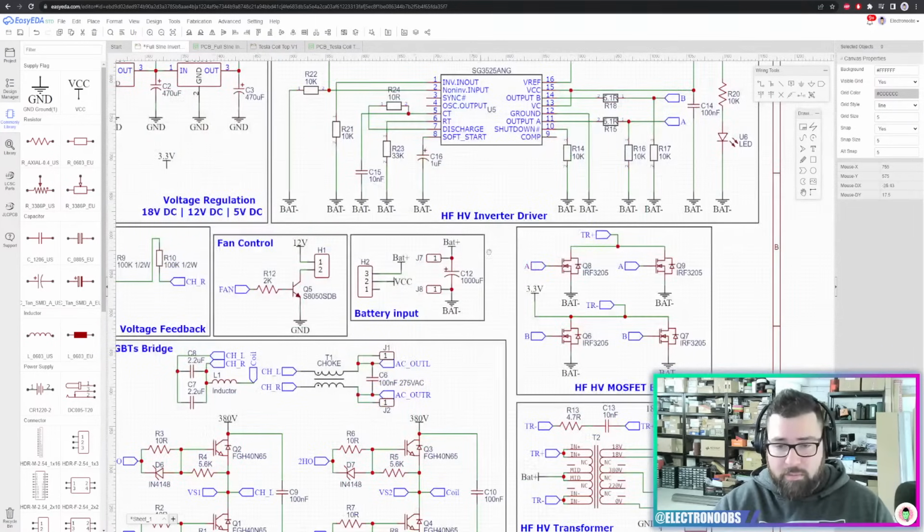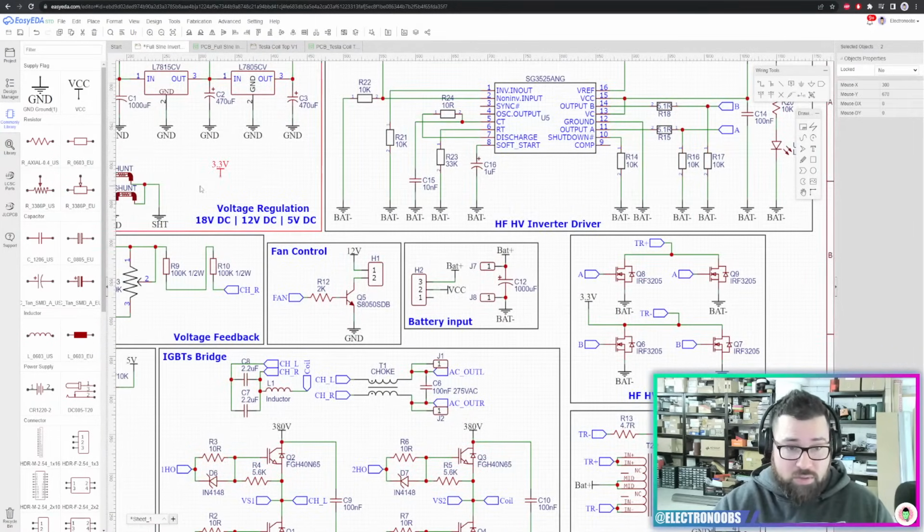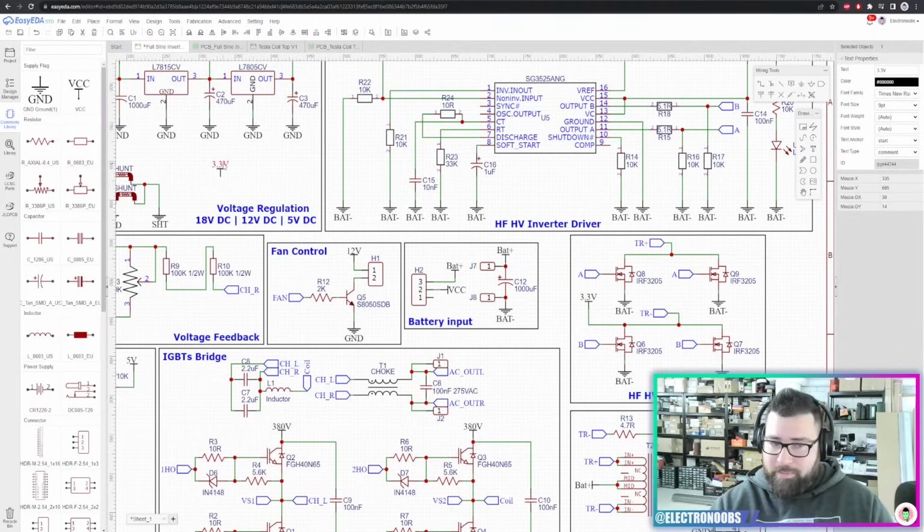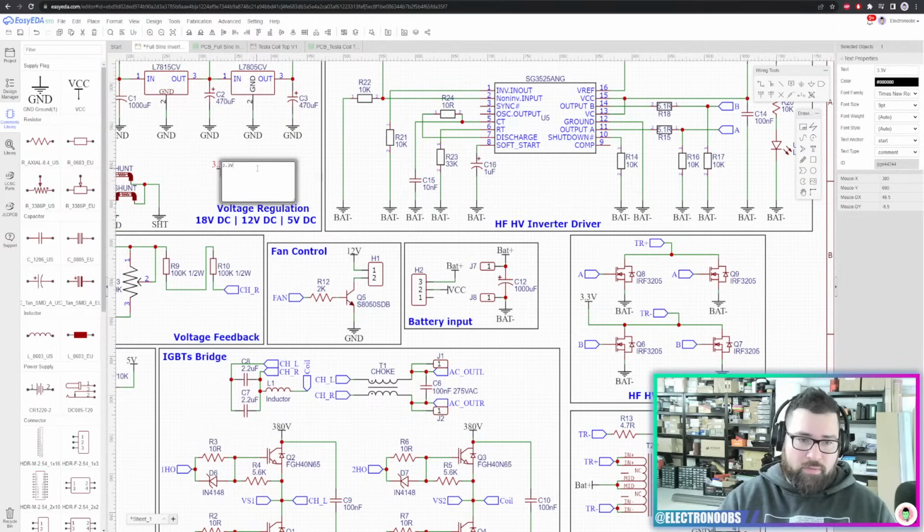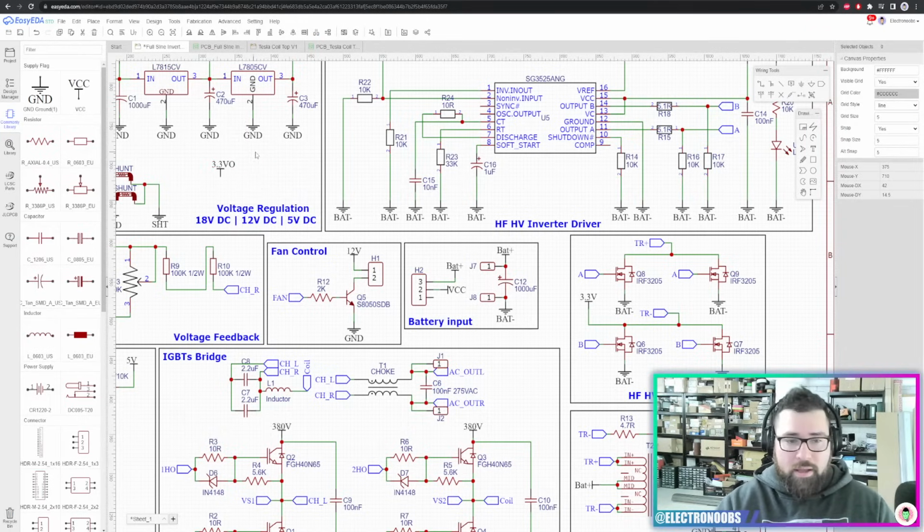So that basically is a virtual connection between this 3.3 volts and this 3.3 volts. But if you change the name here to 3.3 volts and instead of V, just VO, have in mind that this is not the same as this one, because the connection is made with the name, so they have to have the same name. So let me just delete this here and this here and show some real examples.